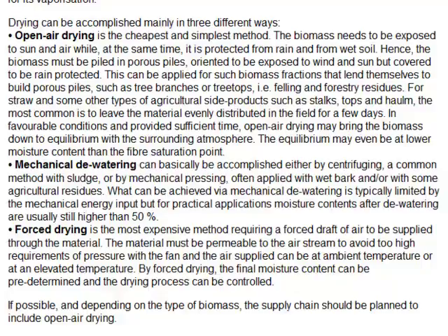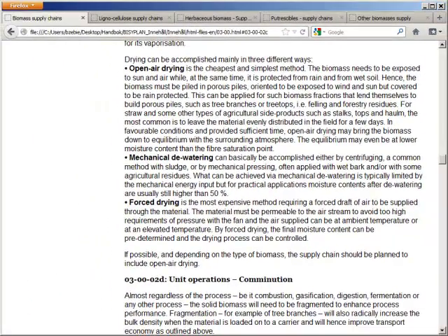It's very expensive, and it's also quite dangerous, because even low temperature heating of biomass material may, if the material is contaminated, lead to ignition. So avoid forced drying both for economic reasons and for risk reasons as far as you can, and try to plan the supply chain so that open air drying can be accomplished.